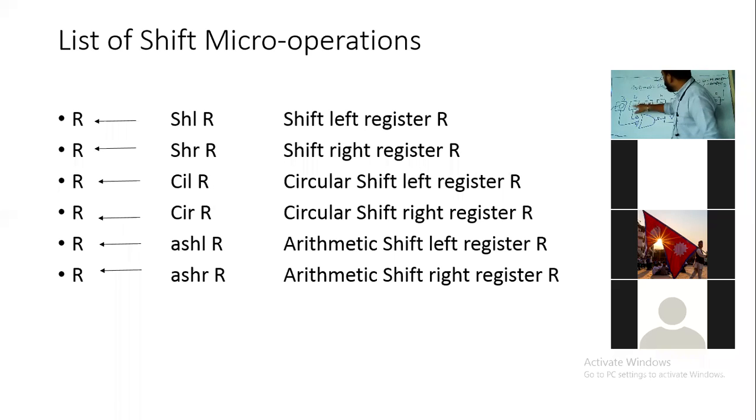Now suppose bit number 6 is 1. What will be the output? Now we have 1 0 to the XOR gate, and the output will be 1. I told you, if the inputs to the XOR gate are not the same, 1 0 or 0 1, then the output will be 1. Remember this. Just remember that if both XOR gate inputs are different the output is 1, and if they are the same the output is 0.